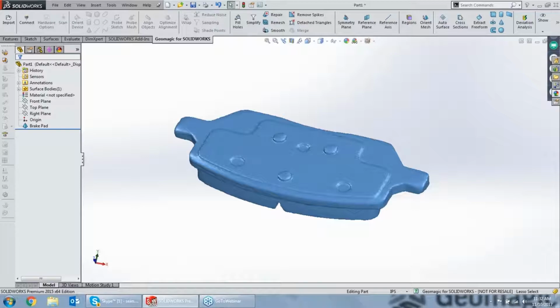consideration is actually do the second of the two workflows that Ian was talking about earlier, where we just say, here's my scan data. It's a series of triangles in this STL format. Let's just wrap them in a series of NURB surfaces and do a very quick and very accurate conversion to CAD so that I can design a new component around this.